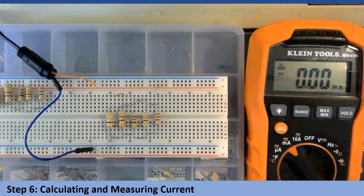As we learned in our first lab, when resistors are placed in series, they act to divide the voltage, basically by segmenting it with each of the voltage drops. On a parallel circuit, we've already discovered that the voltage is the same. So because we have different resistors, it must mean that it becomes a current divider.